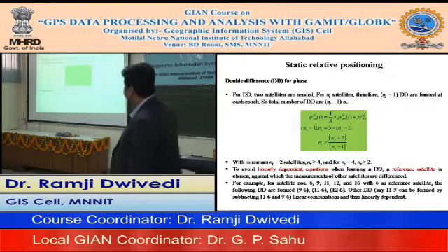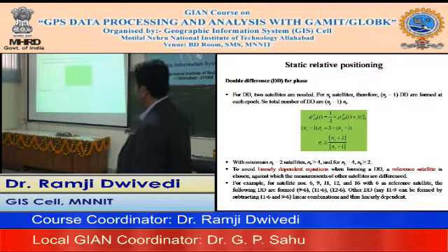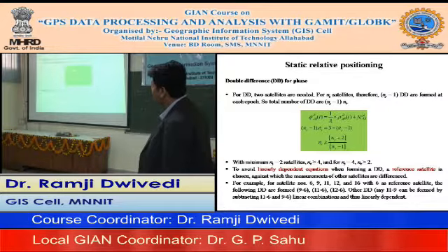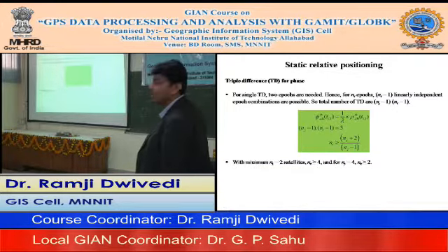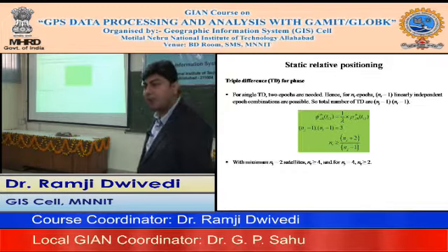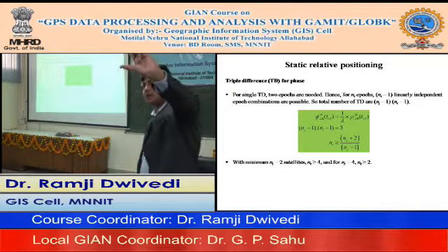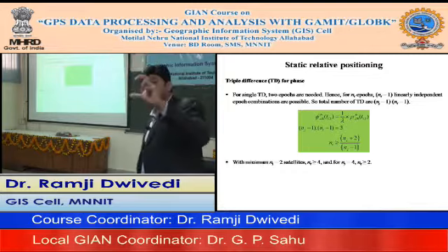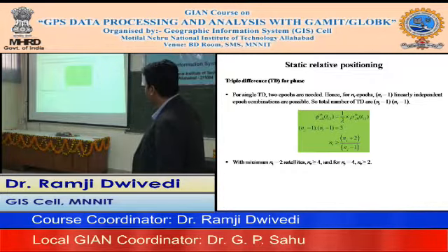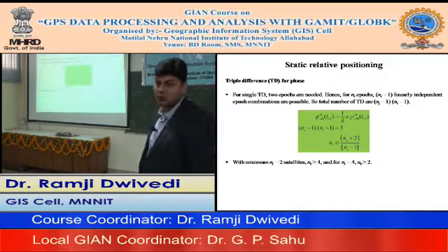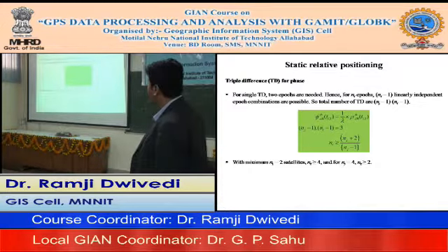Okay, so for triple difference, now not only are the satellites reduced by 1, the epochs are also reduced, because primarily you have 2 epochs and a final observable of 1 epoch. So that's why Nj minus 1 into Nt minus 1, both at the same time. This is also straightforward: Nt should be greater than Nj plus 2, Nj minus 1, and then you could see that for the minimum of 2 satellites you need 4 satellites to be available.